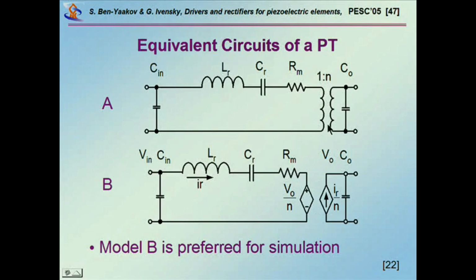The reason is that the way in a simulation you would describe a transformer will be by putting, say, two very large inductances here. Now, for DC, these inductances are short. This is not happening in the real transformer. There's no short for DC in between the electrodes. So therefore, if you use it for, say, a doubler, a rectifier, you'll get erroneous results because there's no blocking.